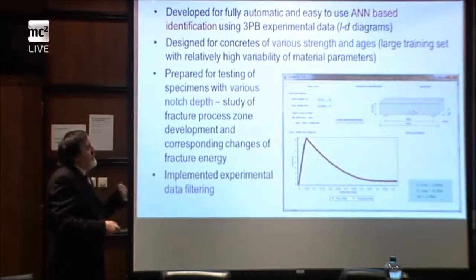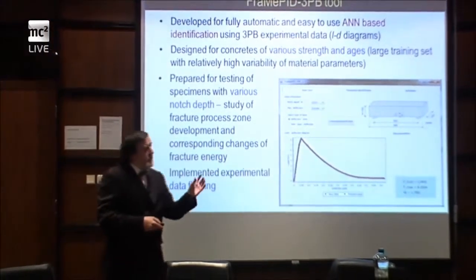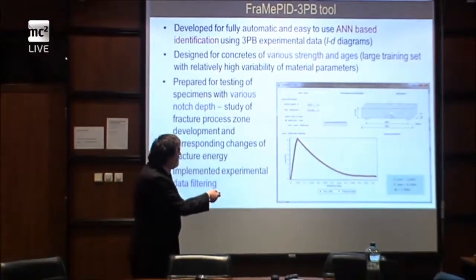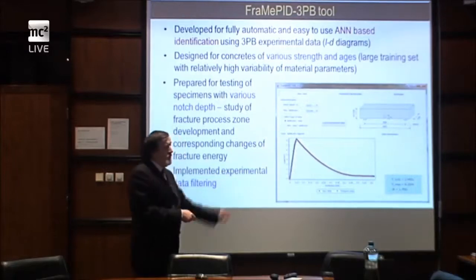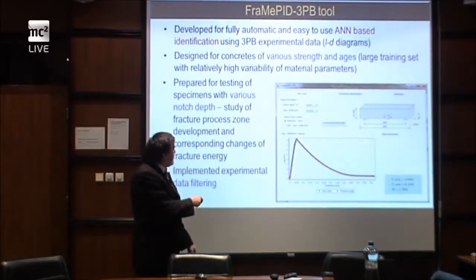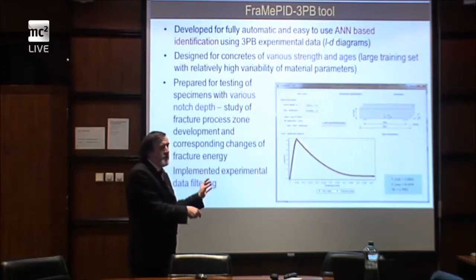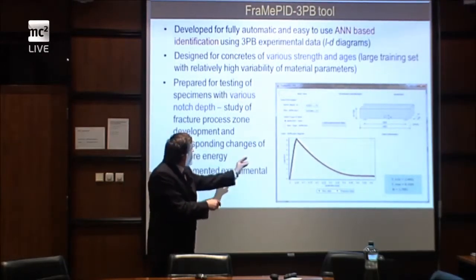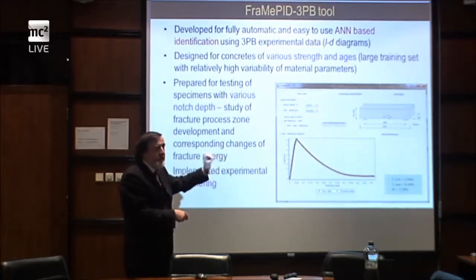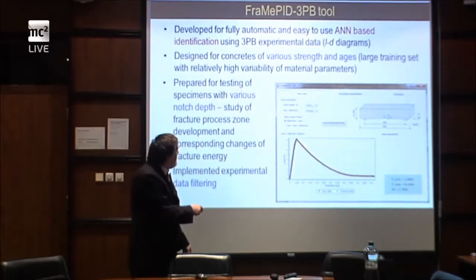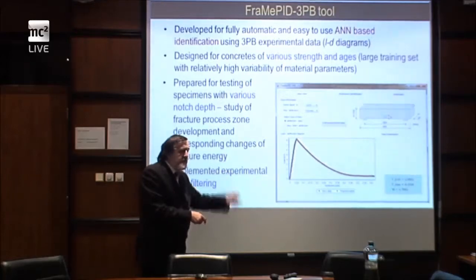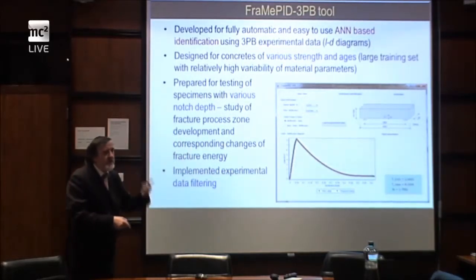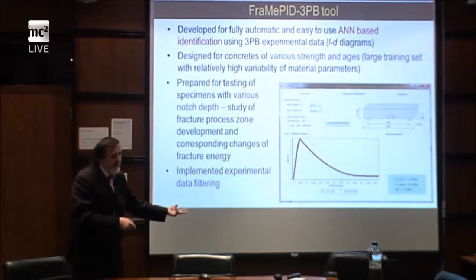So the aim was actually to develop the tool where if you go to the laboratory, you produce a load-deflection curve, you put the load-deflection curve in the software, and in the software the artificial neural network is directly implemented, and the software will tell you immediately what is fracture energy, what is tensile strength, what is compressive strength, etc.